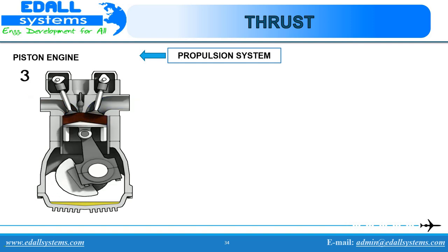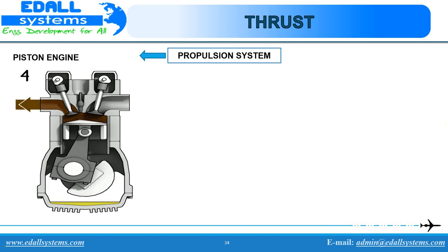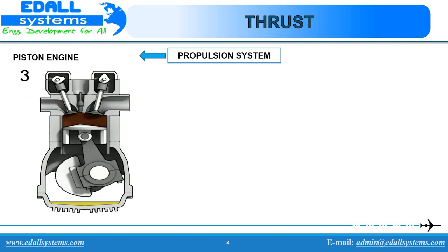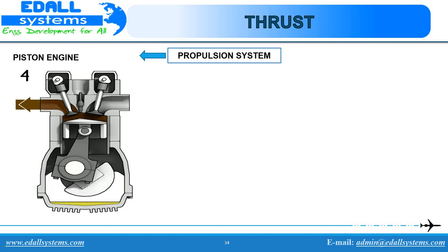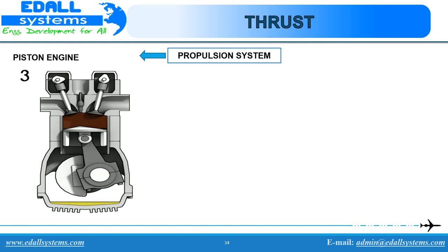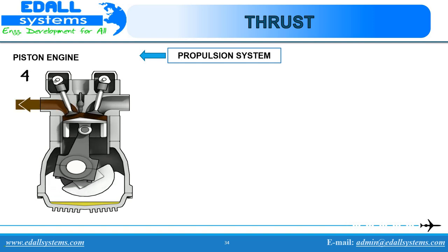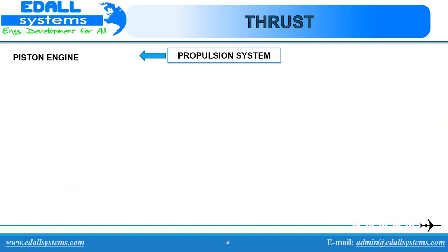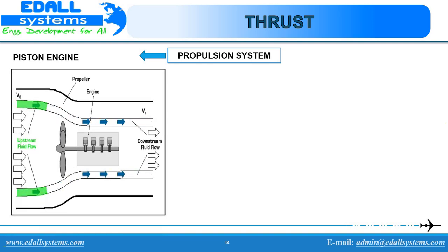Compression. The piston then gets pushed to the top, compressing the fuel mixture and igniting it via a spark plug. Ignition. The ignition pushes the piston downwards, providing useful work to the engine. Exhaust. The waste chemicals get output through the exhaust port and the cycle repeats. While there are many kinds of internal combustion engines, the four-stroke piston engine is one of the most common.